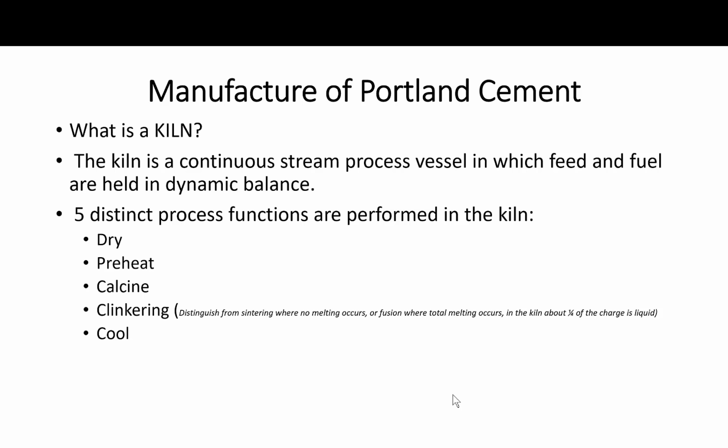As the raw material of limestone, clay, shale tumble toward a flame of about 1600 Celsius. This is the temperature of the flame, not the melt inside the kiln. A chemical reaction transforms them into the material we know as clinker.